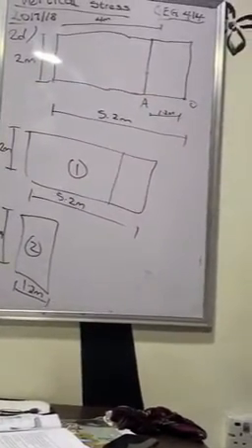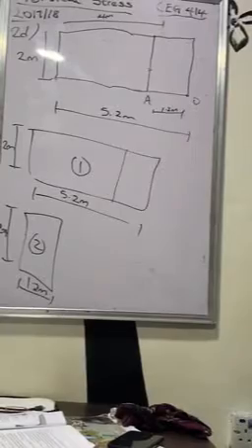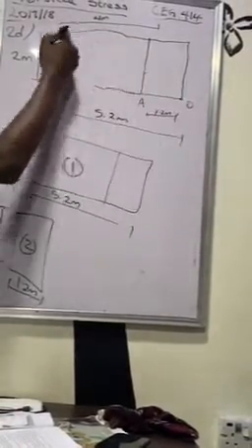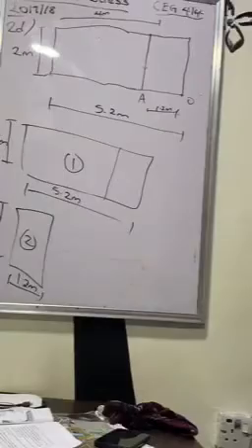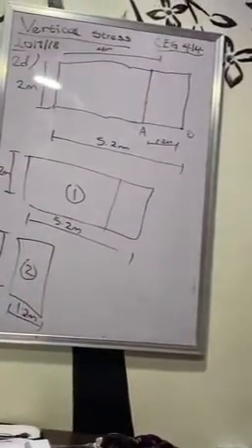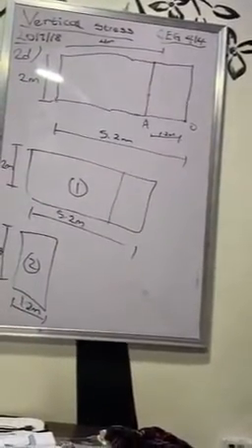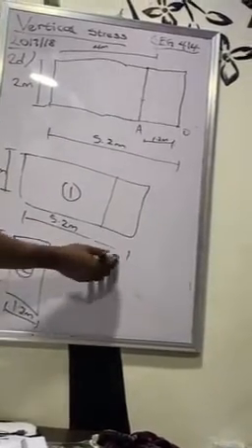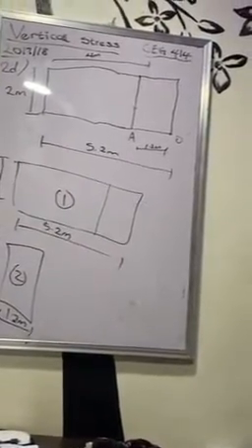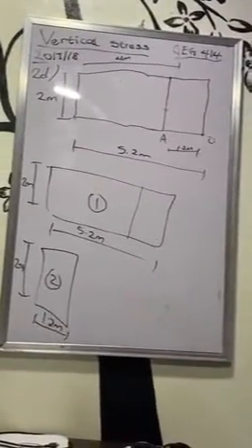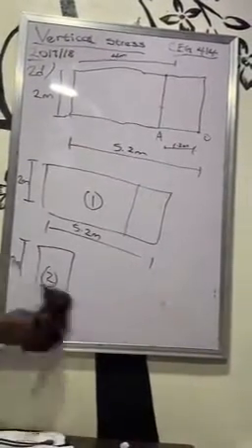That's the logic for when you are looking for vertical stress at a point outside the footing, outside the foundation, outside the 4x2. You find for the big rectangle subtracted by the one for the small rectangle. In this place now, we can see that our L is going to be 5.2, B here is going to be 2, our L here will be 1.2, our B here is going to be 2. So it's quite straightforward actually.